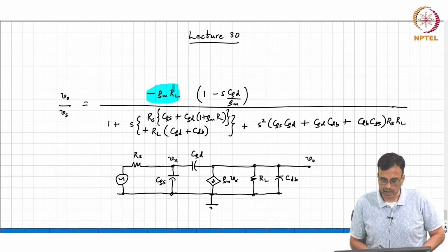We also recognize that even though there are 3 capacitors, the denominator polynomial is only second order, and that's because there is a capacitor loop. Finally, we are also happy that all the coefficients of the denominator have the same sign, which means that the system is stable, right? That means all this effort so far was worthwhile, because if this was not stable, then we might as well pack our bags and go home.